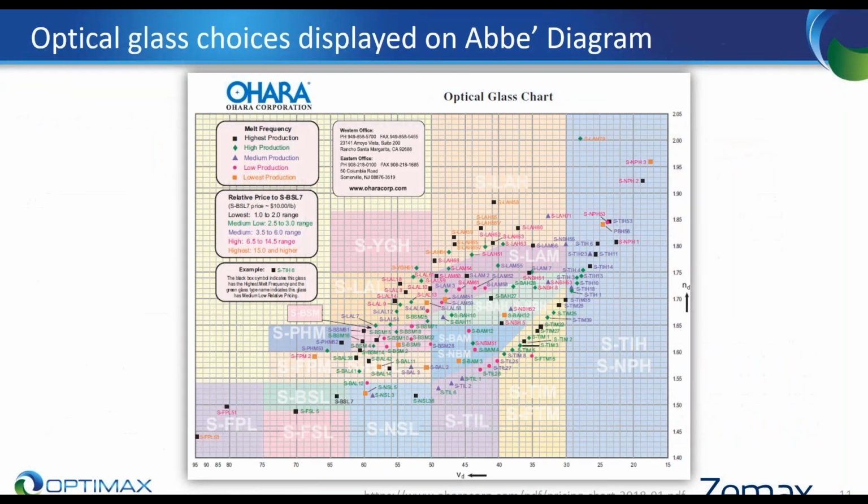So this next slide here, switching gears a little bit into other aspects about the material, looks at an Abbe diagram. I'm fairly certain many of you are familiar with the Abbe diagram, where it shows your index and your dispersion, or your Abbe value, on the two different axes. This is also referred to as a glass map, and many manufacturers offer this in order for optical designers and fabricators, or anyone interested in these materials, to be able to look at all of the glasses available. It's very common to see it in this teardrop shape crescent across the map.